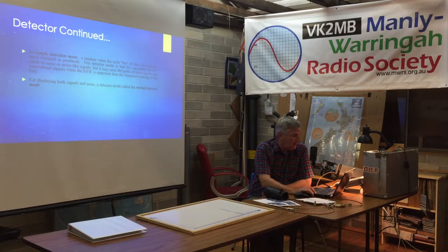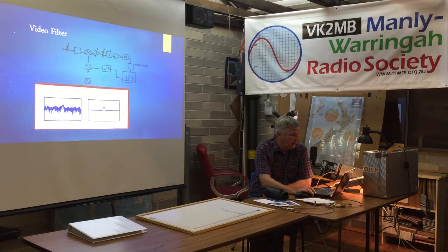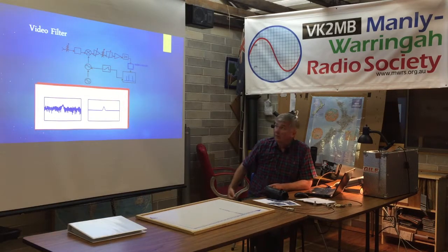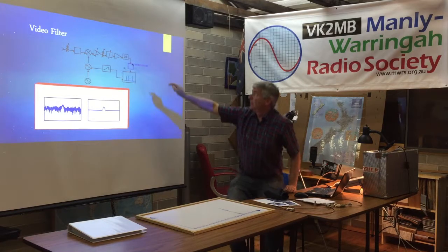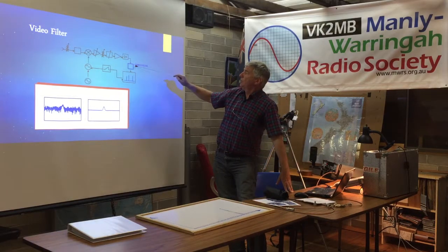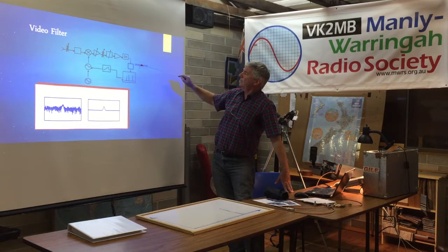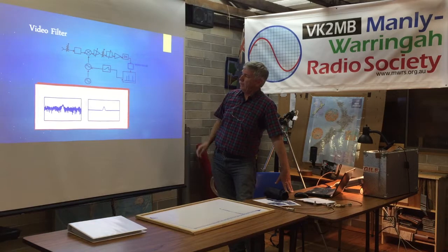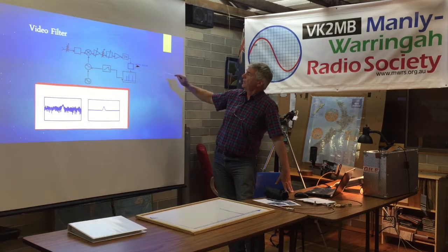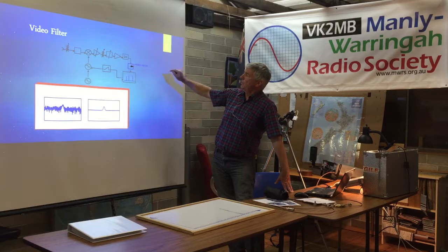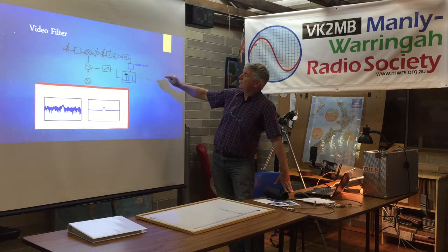Okay, and this sample, right, just move on. Oh, the video filter. So, Phil, you asked about video filter. There is another filter, which is after your detector, which is called the video filter. And it's a strange thing. I remember when I first started, I couldn't understand why the word video was used, but really all that's referring to is it's the filter before it goes to the video display.